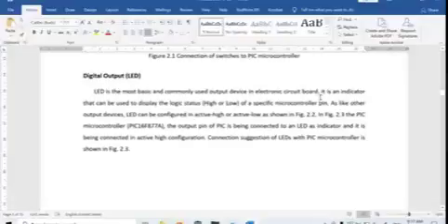So we use LED to indicate or display the logic high or low from a specific microcontroller pin. By connecting an LED to a specific pin, we can observe the output of the microcontroller, whether the signal is producing high or producing low.